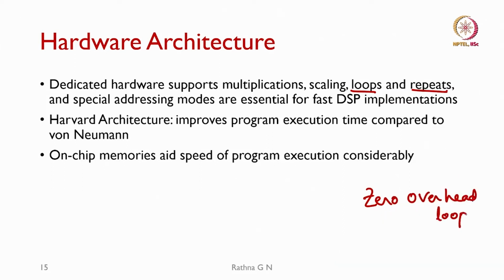If I define my variable with hash assign or anything, which we will discuss in the lab, and I declare some value, I know how many times the loop is actually going to run. If I say 40, then I will be repeating the instruction 40 times. I need not spend time on decrementing, as everything happens in the background, and I need not spend any time on the loop to come back.